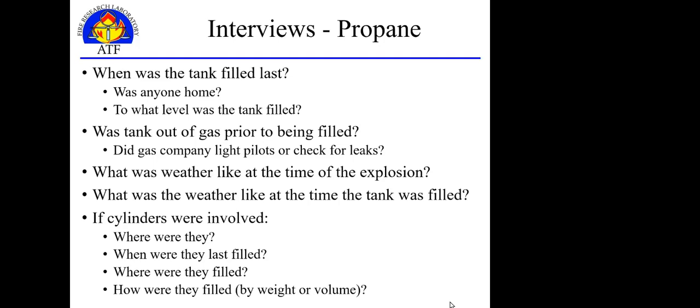If you overfill a tank because you don't know how, and let's say you fill it on a cool day, but then you put that same tank out in the hot sun, the pressure in that tank is going to increase. And if you don't leave enough vapor space for that gas and vapor to expand inside the tank, you can actually overpressurize that tank and cause it to fail just from the solar gain heating the product inside.